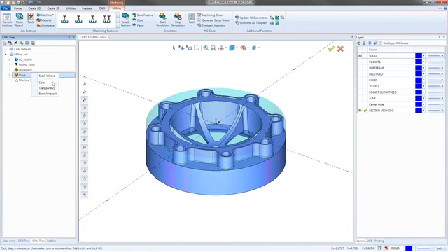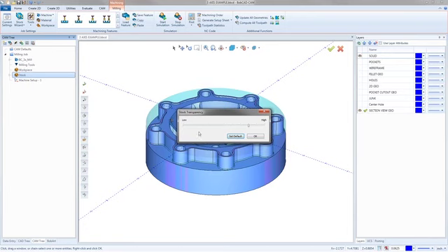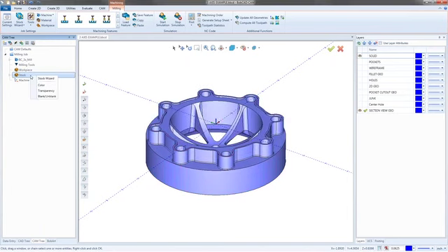So the easiest way to do it is to go down to transparency. If you bring your transparency to the right, it'll make it a higher transparency. So it makes it more easily see-through, I guess is the easy way to put it. It becomes invisible if you go all the way to the right. It blanks it out completely. And if you do that and you set the default as that, you'll never see stock.